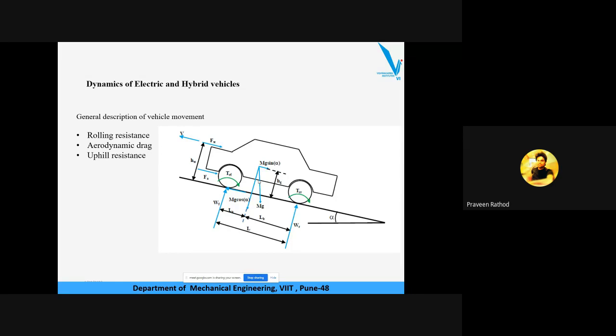Here we have to consider all necessary forces according to the equations of motion, including all the forces that help in moving the vehicle forward. These propulsion forces help the vehicle overcome the forces that are acting on it. Which forces are acting? Some resisting forces. Why are these resisting forces acting on the vehicle? Due to gravity, such as air resistance and tire resistance.